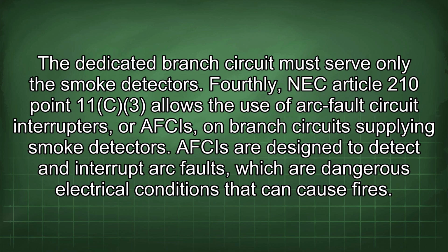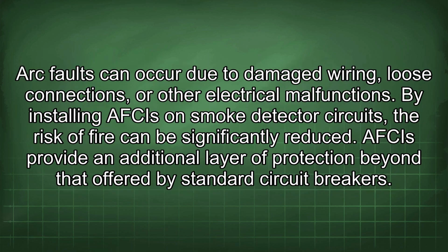Fourthly, NEC Article 210.11(c)(3) allows the use of arc fault circuit interrupters, or AFCIs, on branch circuits supplying smoke detectors. AFCIs are designed to detect and interrupt arc faults, which are dangerous electrical conditions that can cause fires. Arc faults can occur due to damaged wiring, loose connections, or other electrical malfunctions. By installing AFCIs on smoke detector circuits, the risk of fire can be significantly reduced. AFCIs provide an additional layer of protection beyond that offered by standard circuit breakers.